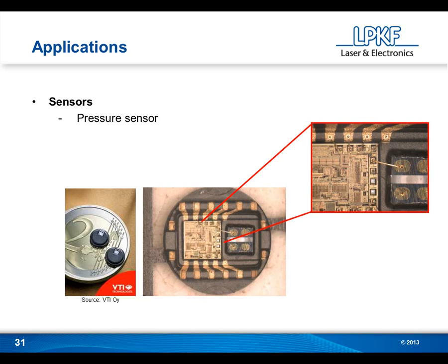But you probably noticed the absence of a lead frame in this part. The semiconductor is directly wire bonded on the traces that are on the plastic housing that are created in the LDS technology. So again, we forego other parts. We reduce the parts count. We really start to become three-dimensional on this because the traces from the landing pads, from the semiconductor, from the wire bonding, go straight up the walls and up to the top where they become the pads for becoming an SMT component. So again, there's a great use of making a very small part.